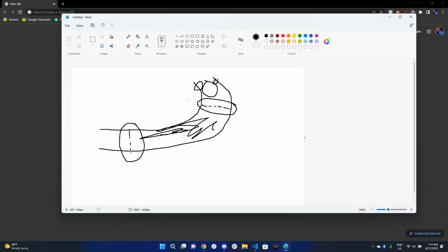So it's effectively allowing us to manage the state of our robot, to see how many balls are within the robot at once. And that's pretty useful, right? That's information we can use within our robot to determine how many balls we're actually shooting, and whether we're allowed to intake a ball, because we can't hold more than two balls at once. All of that is why beam breaks are useful.